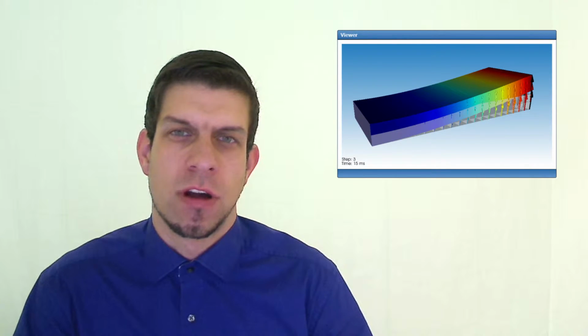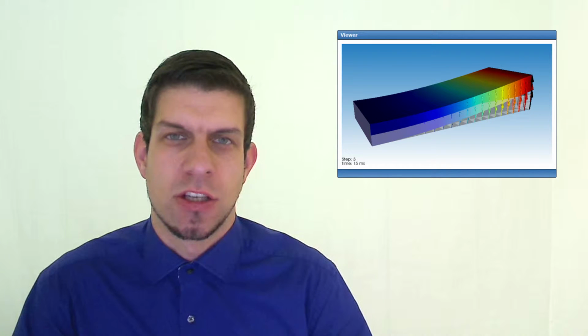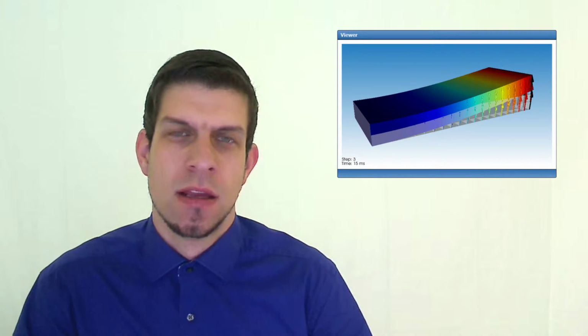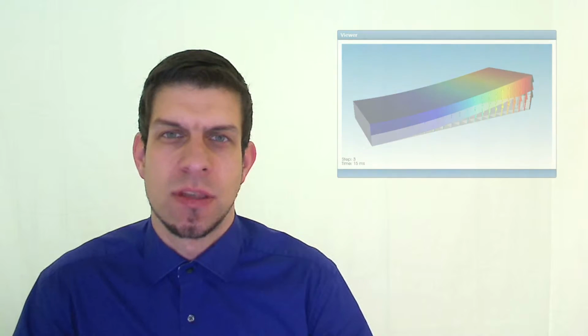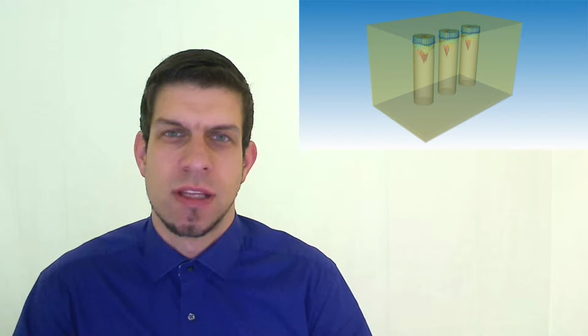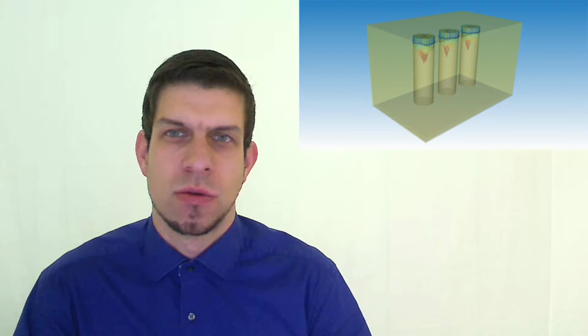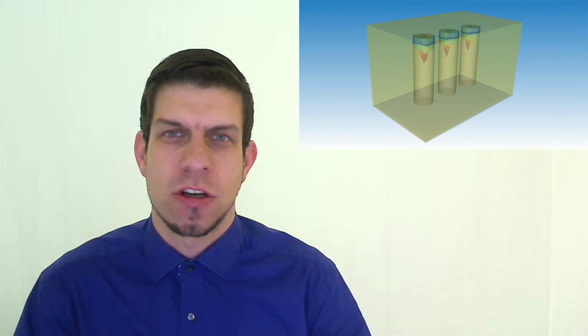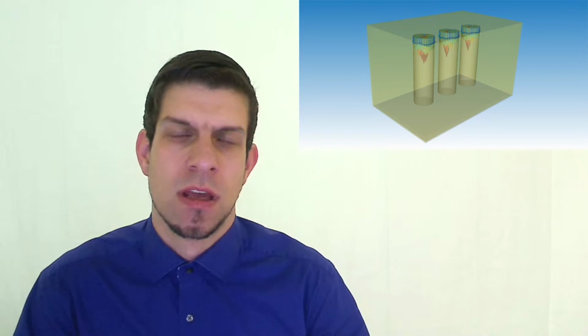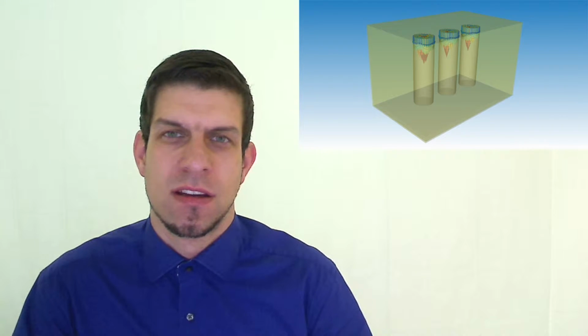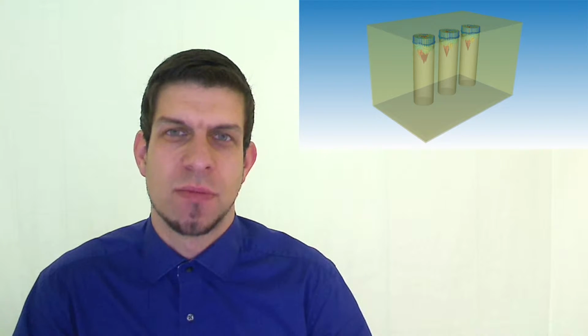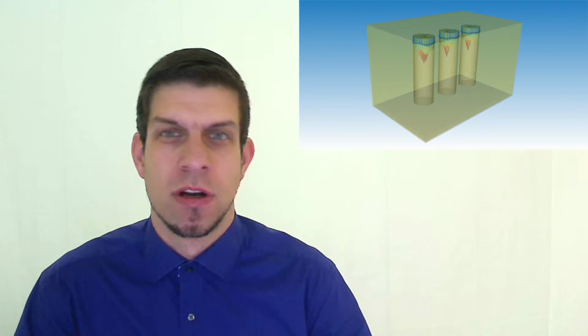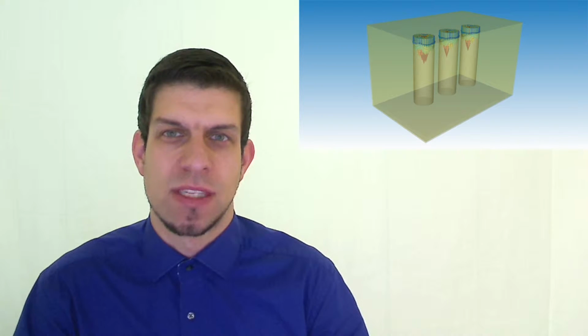In the mechanical domain we were able to introduce support for nonlinear geometric behavior. That means if you've got large deformations, then you should use that nonlinear formulation in the mechanical domain. Also in the mechanical domain we introduced support for prestressing. So prestressing means that you have got a first static step where you do a certain computation and deform your structure using a force or maybe a prescribed displacement, and the resulting stresses will result in a modified material behavior that can be taken into account for further harmonic or eigenfrequency analysis.